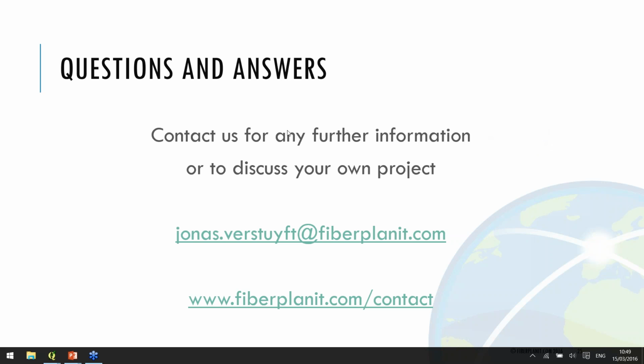Let's have a look here. One question is how the fiber concentration points or distribution cabinets are placed. The software uses the information that was specified in the rules. There you can specify a restriction on the total size of a cabinet, and also a cutoff distance, the maximum distance from the building to the distribution cabinet. Then it will divide the complete area into different clusters and place the cabinet in an optimal location.